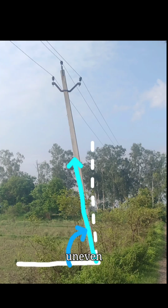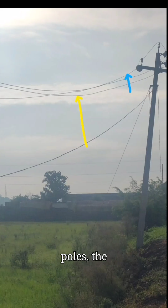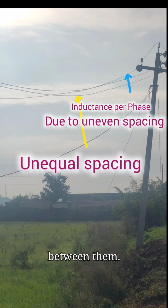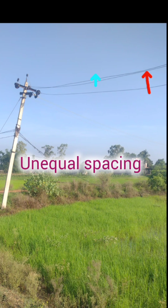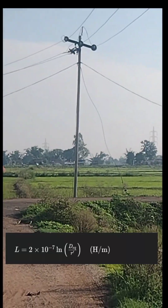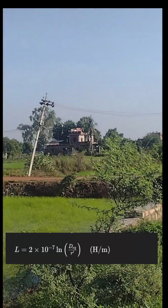Inductance per phase due to uneven spacing. As we can see, these electrical poles, the conductors coming from them, these three conductors have unequal spacing between them. Let's use the formula. L is equal to 2 into 10 to the power of minus 7 log D equivalent by R dash Henry per meter.